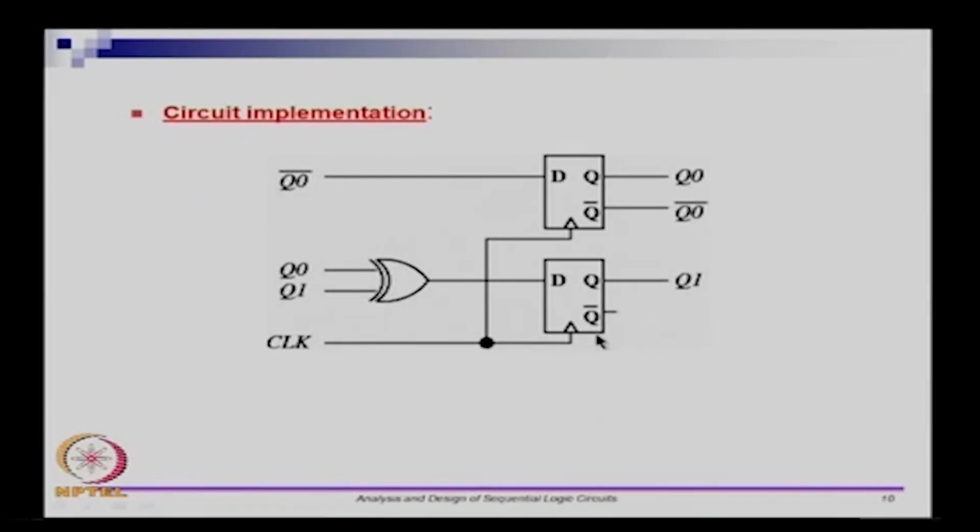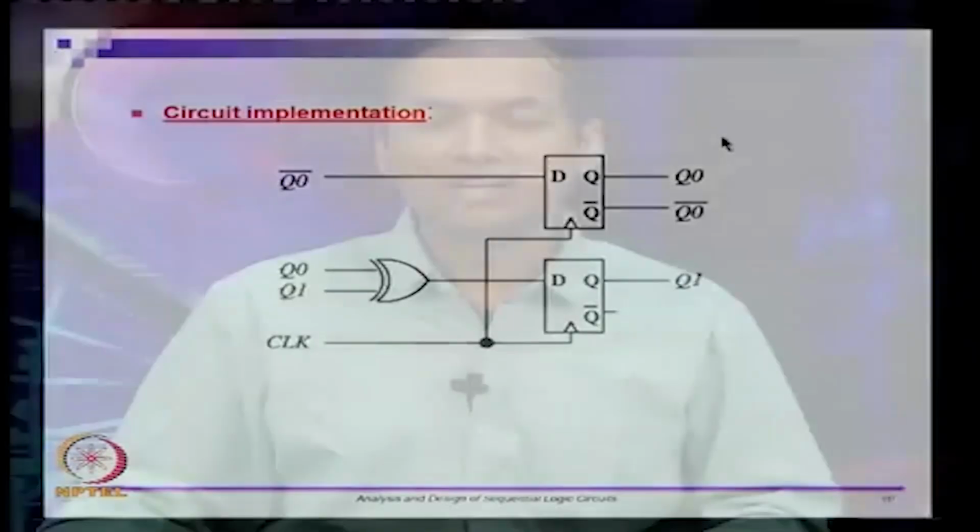So you can see that this resembles the canonical circuit. You have a state register and the input forming logic, but there is no output forming logic, it is just the wire. So it resembles the canonical circuit, except that you do not have the output forming logic, and the input forming logic on this line is either the line itself or an inverter. So what we did is something very simple. We started with analysis, and now what we did is synthesis.